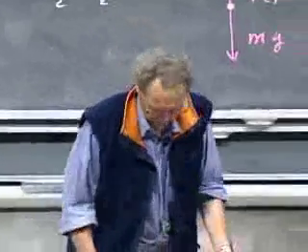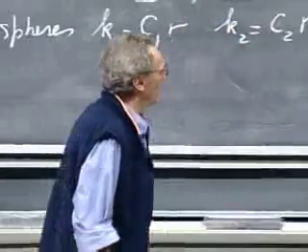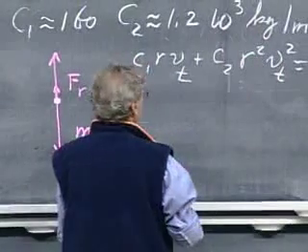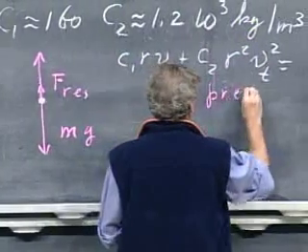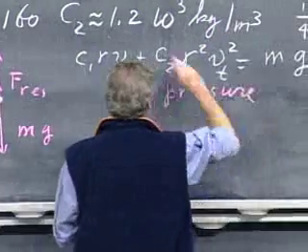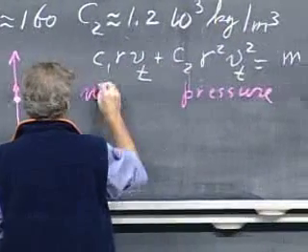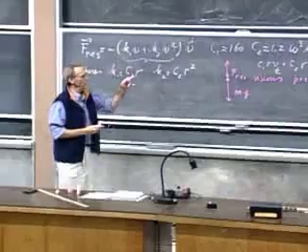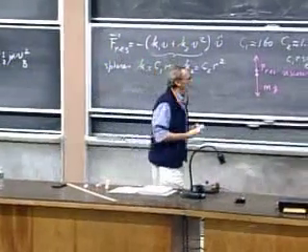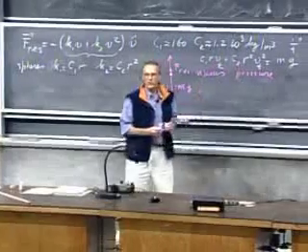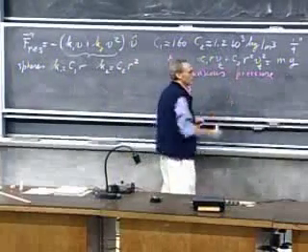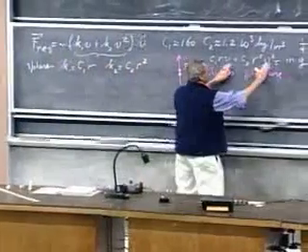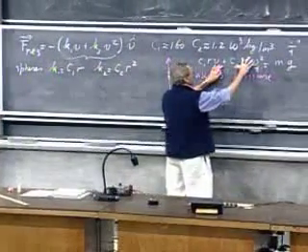But if you did that, that would be a silly thing to do. And the reason why that would be silly is that I claim that this term, which by the way we call the pressure term, can be completely ignored compared to this term, which we call the viscous term. How do we know that that pressure term can be ignored? Well, let's first ask the question, when is the viscous term and the pressure term the same? For what velocity? So forget for now that here are t's. We just want to know that this term is the same as this term.